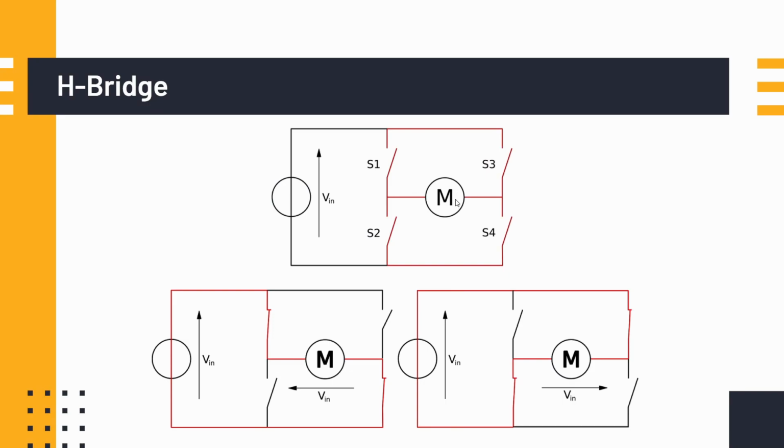So let's say you set both AIN1 and AIN2 to low. That's going to say that, okay, all these switches are open. Then let's say you set AIN2 to high and then AIN1 to low. Let's just say AIN2 corresponds to S3 and S2 here. So if you set AIN2 to high, that's going to close these two switches. And then AIN1 to low, it's going to keep these switches open. And then do vice versa, your motor is going to spin in the other direction. Right, so those are going to control your direction.